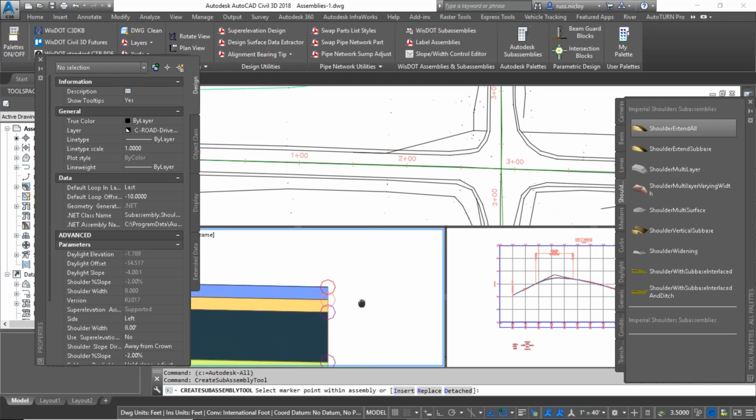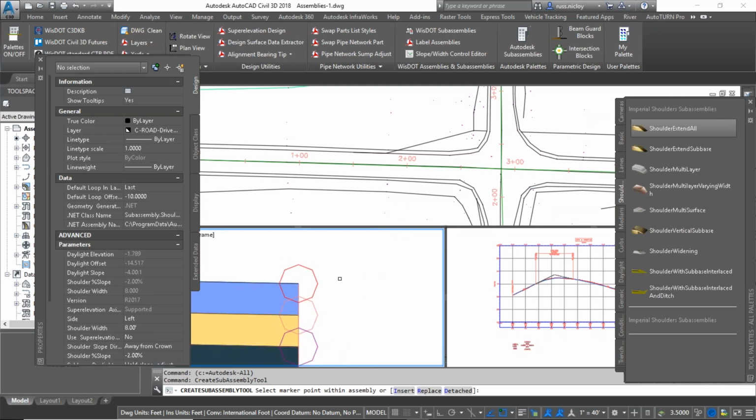But what you do want to do is make sure that you zoom in on the circle points or the point codes of the assemblies and make sure that you attach to that. Now, this is the correct way to connect things. Anywhere on the circle or that point that is not overlapping something else. If you grab in this area here, there's a very real possibility, because of draw order considerations, that you'll be grabbing the subassembly part instead of the point code, or maybe a different point code. Now, a lot of those problems are easily found because you're snapping to something very different and it jumps to a different part. It's not what you expected it to do immediately.